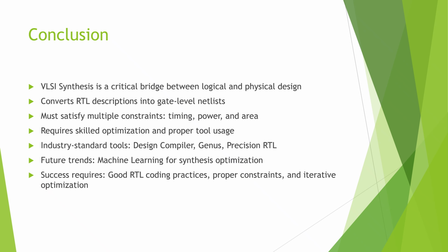Let us wrap up everything we have discussed. VLSI synthesis is the critical bridge between your RTL and the real gate-level hardware that goes into silicon. It reads your RTL, uses libraries and constraints, optimizes the design, and produces a netlist that aims to meet timing, power, and area goals. It fits into the flow after RTL simulation and before physical design, and it's used heavily in ASIC, FPGA, and SoC projects.